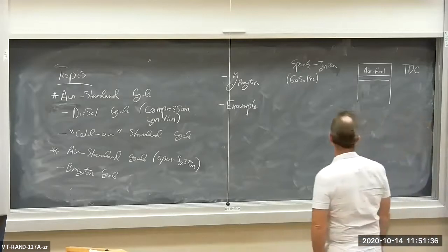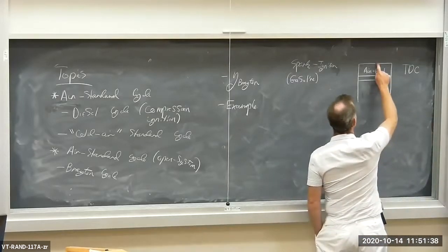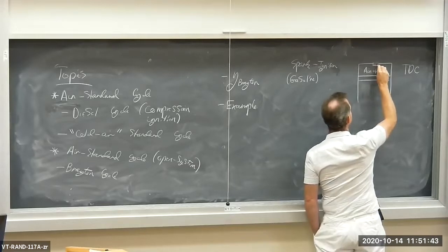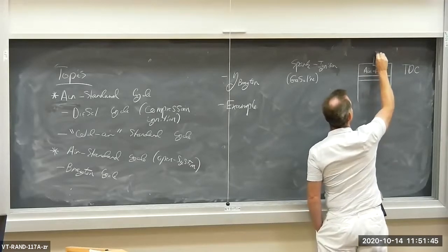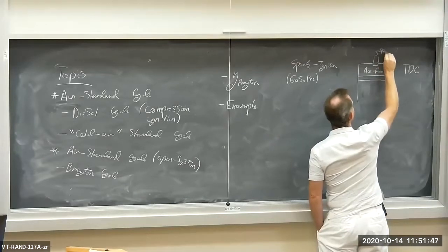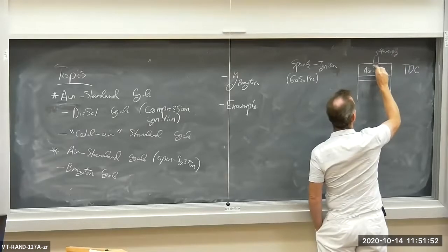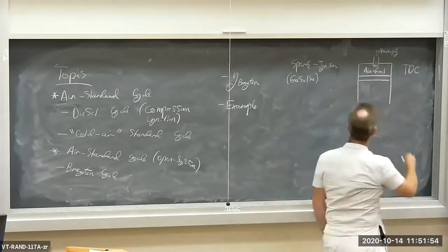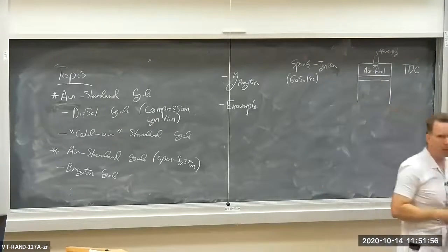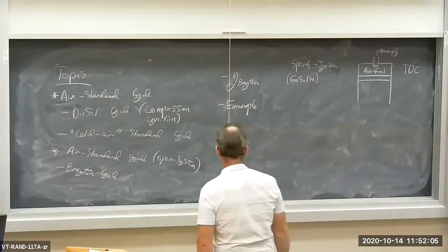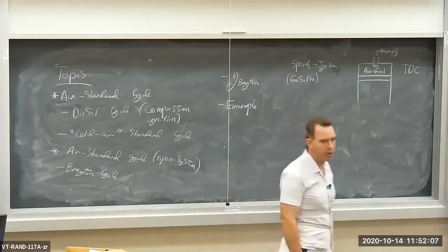Isentropic compression, if you like. And we have a little spark plug up here. A little spark occurs, and the air and fuel start to burn. Now the air and the fuel burn so quickly that we can model the reaction, and therefore the heat addition, as one of constant volume heat addition.